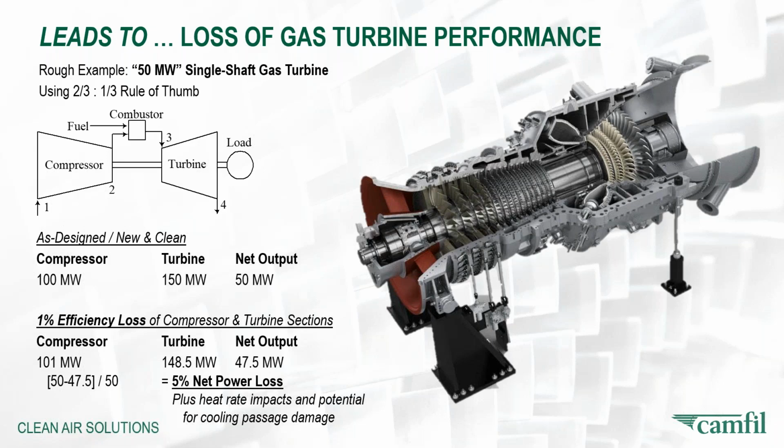What happens to that 50 megawatt gas turbine if we have a 1% efficiency loss in both the compressor and turbine sections due to, say, inadequate control of airborne contaminants and such? Well, the first thing that happens is that the compressor, instead of needing 100 megawatts, will need 101 megawatts to do the same kind of work. The turbine itself lost 1% of efficiency, which is around 1.5 megawatts. And look where the net output has dropped from 50 megawatts to 47.5 megawatts, which amounts to a 5% net power loss on that 50 megawatt machine.